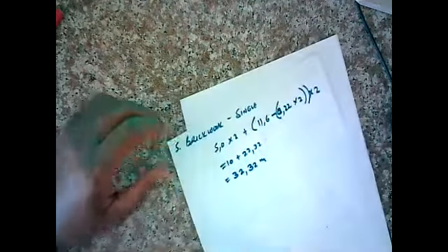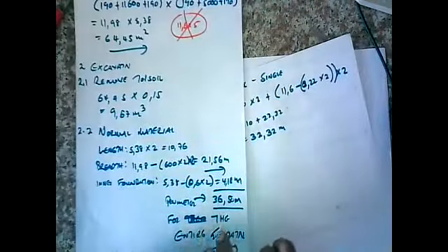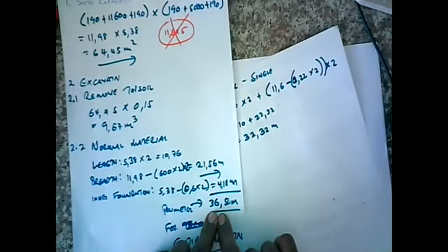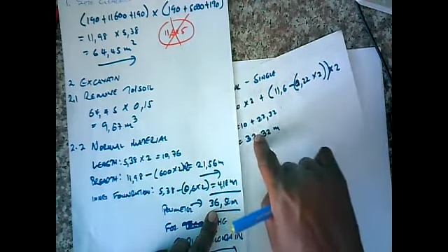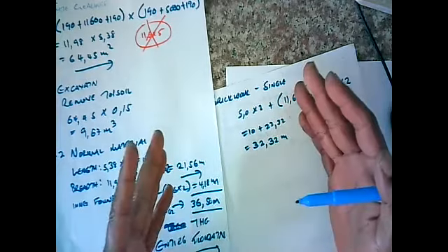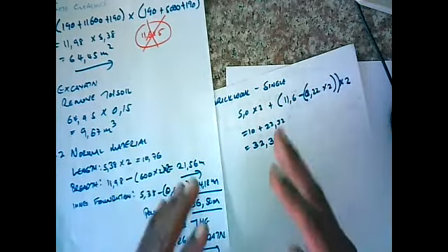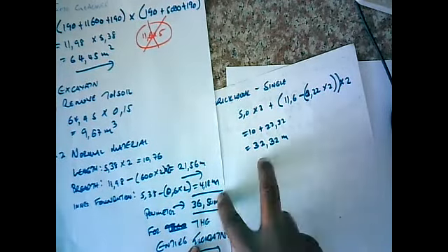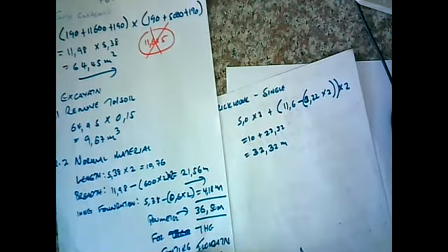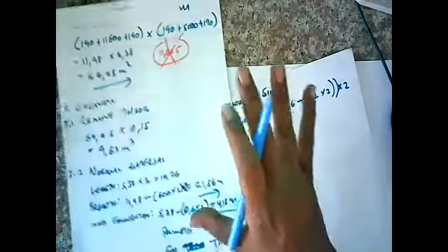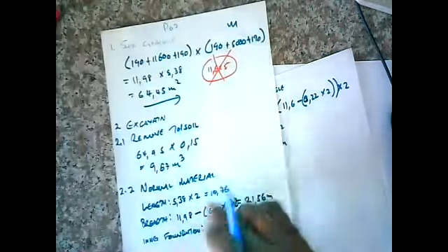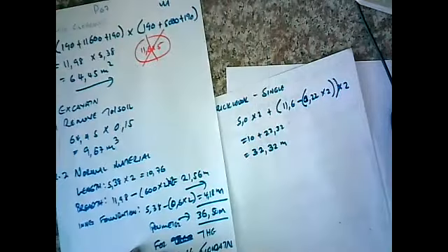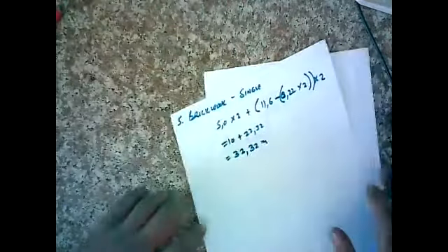Okay, let's check something out. Notice the perimeter for side clearance, or perimeter for our foundation, is 36, much more than the perimeter for the brickwork. And it's obvious why. As a simple check when you're doing your assessment or writing your exam, if it's the other way around, something's wrong. Just don't progress. Stop right there, and check your answers. Because as you've seen from here, how one number is used consecutively. All right, so there's that.